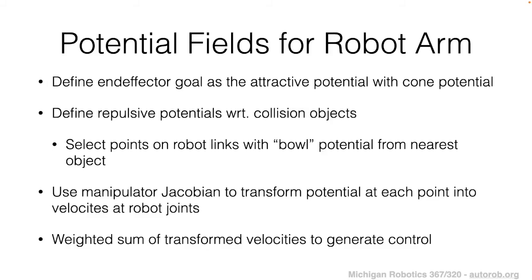One of the challenges with this approach is that at each one of these steps, you're going to have to deal with this larger dimensional configuration space, which could create some challenges when you try to define your potential fields. But conceptually, this approach should work. So another really cool advanced extension would be to implement a potential field planner within our Kinova workspace that would work with the Wavefront planner. That would be another advanced extension that I would be really interested in seeing, and I think it could have some really nice results.